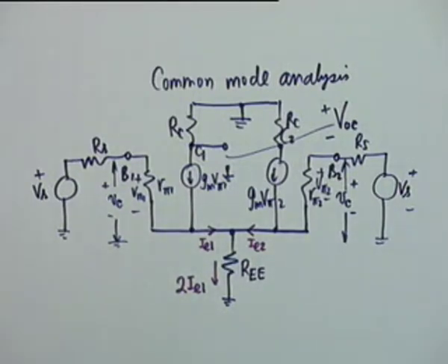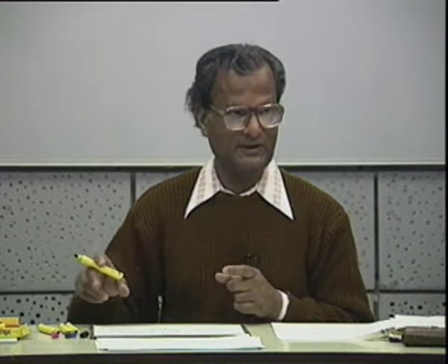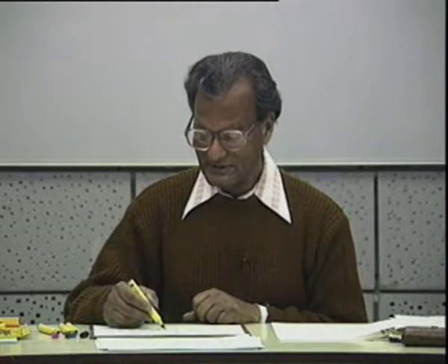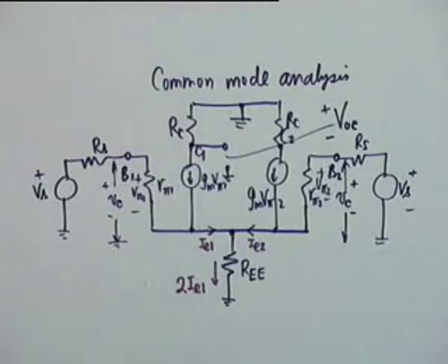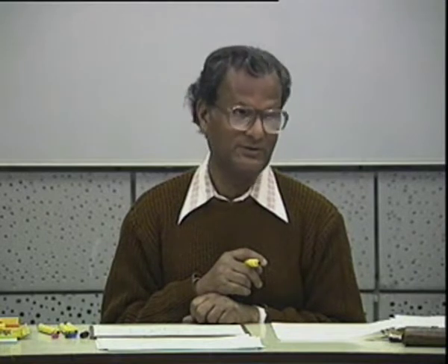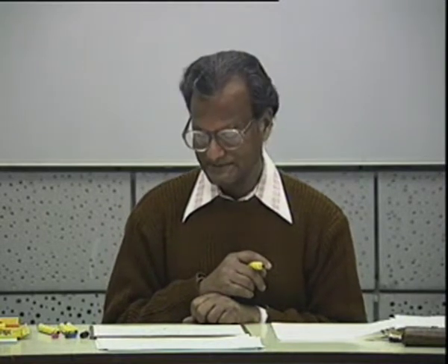Are these two common emitter amplifiers connected cascaded to each other? No, that's a major mistake. They are emitter coupled. When two amplifiers are cascaded together, the emitters are not necessarily common. Here we have taken pains to connect another resistance. There is a great difference. If they were two common emitters, then all these advantages would have been lost, you would have needed coupling capacitors and many other things, and the signal to noise ratio would not have been improved.